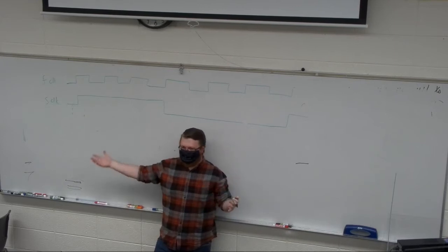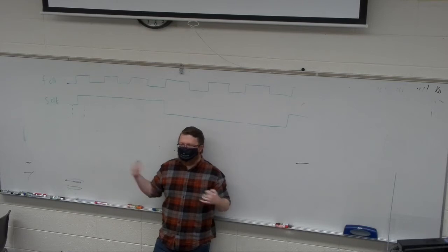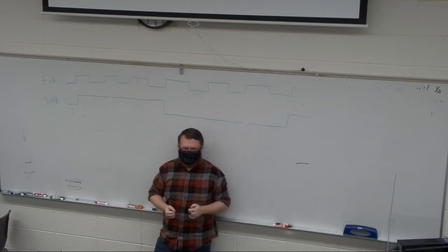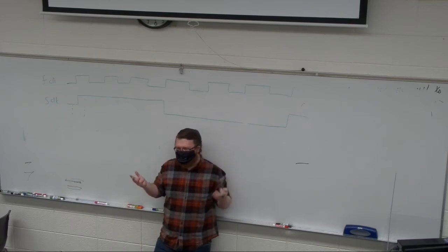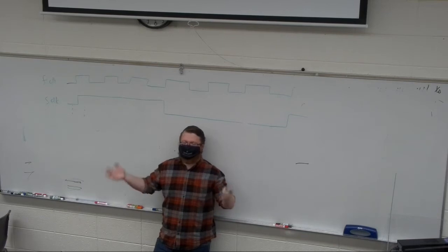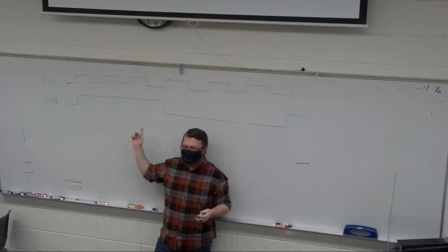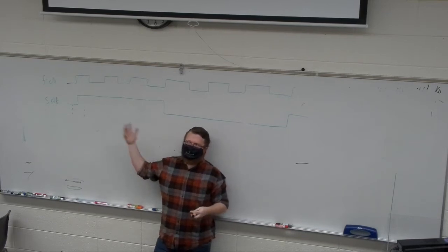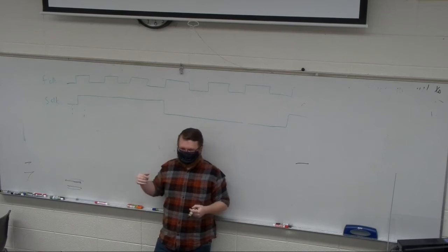Now, you can start extrapolating this out to larger bit numbers, right? So if I'm sending out 100 kilobytes of data, suddenly 1% clock drift is a problem. But an 8-bit UART packet with 1% drift, who cares? So obviously you can calculate when the clock drift matters, and you can come up with more advanced algorithms that adjust for clock drift issues.